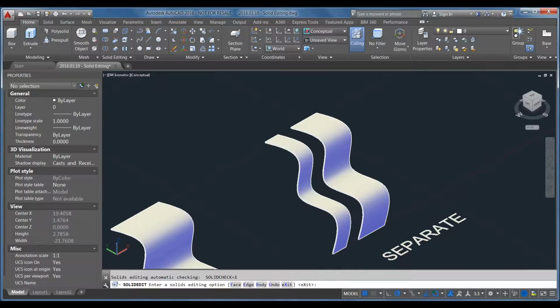If I re-enter that solid edit command, you can get to your edge options. You can copy or color them. And if I enter it one more time, you get a bunch of options for body. This is imprint, separate solids, which is what we just used. Shell, clean, check, undo is always there for you, or exit the command. So just a quick trick. If you're looking for something and can't find it, use that solid edit command.